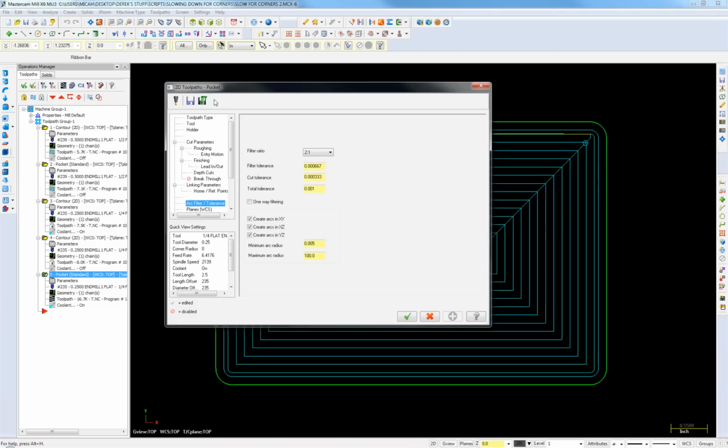I use that for a special situation just because I think it's easier. And technically, with a good post, you don't need to worry about it, but you know what I mean? Right. Usually, what's the point of throwing a G18 or G19 in there to make your G code 10 lines shorter once every 3 months?